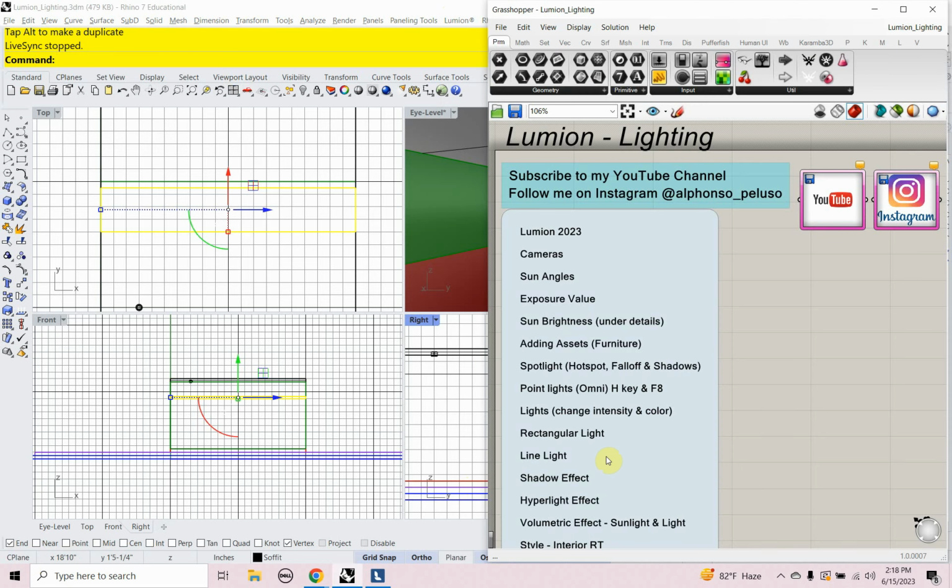So we looked at spotlight, we looked at point lights, we looked at lights changing the intensity and the color. I have the H key here is just a hotkey to raise the light up and down, which in my world is the Z direction, but it's the Y direction in Lumion's world. And F8 will preview the shadows on and off in your viewport. F8 will show you that. So we looked at lights changing the intensity and color. We looked at rectangular light, line light.